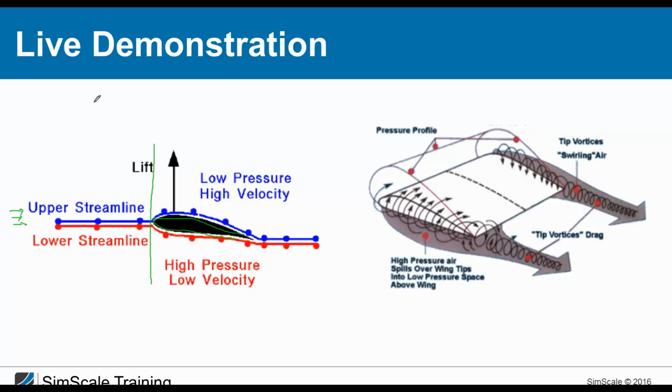And there is the law by Bernoulli, which basically says I have a total pressure, let's call it P total, and this total pressure is made of a static pressure and a dynamic component. This static pressure is, for example, our environment pressure, P0, and the dynamic pressure can be expressed by 1/2 times the free stream velocity, or velocity at the point, squared, multiplied with the density.